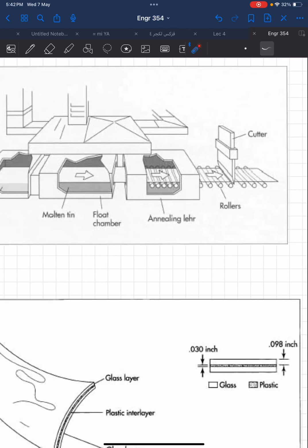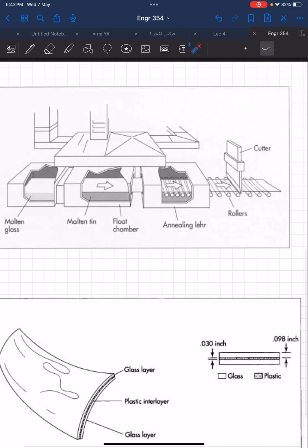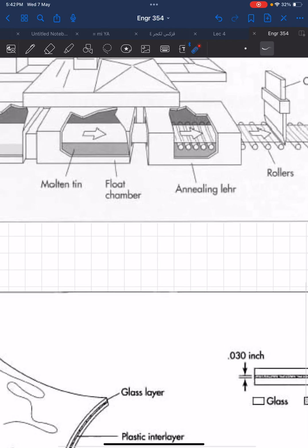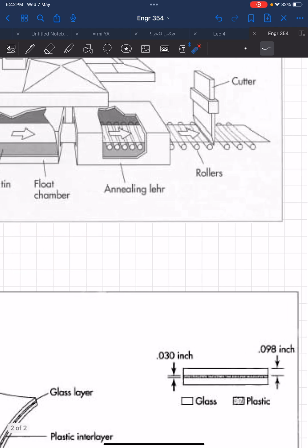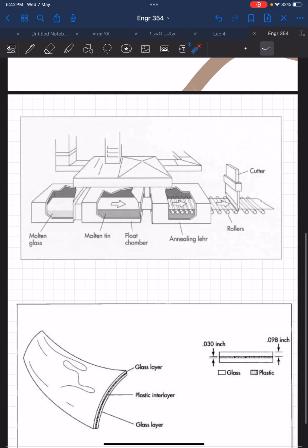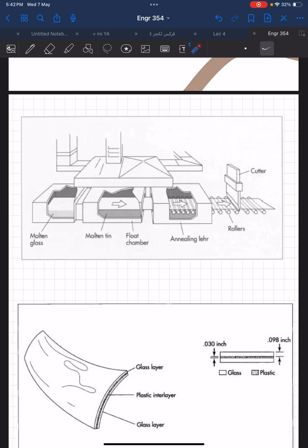Why do we need that exactly? Because when the glass fractures, when we hit it with something or it breaks, this procedure that makes it hard from the outside and ductile and smooth from the inside means that when it breaks, it won't give us a sharp piece of glass. It is a safety thing, and it also makes it harder for the usage. It's for the quality itself.